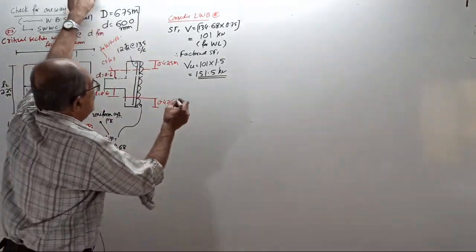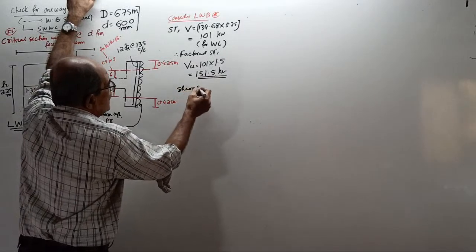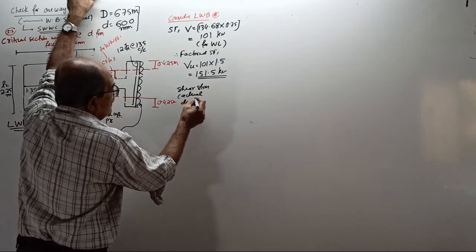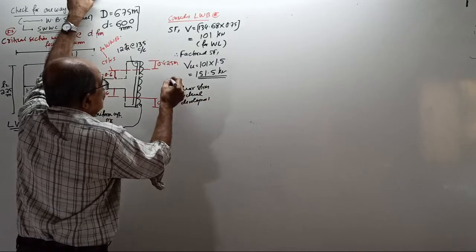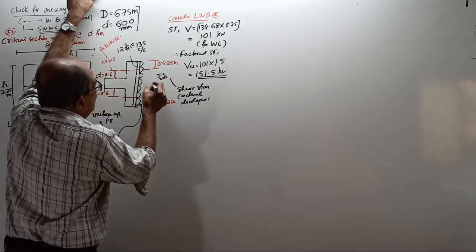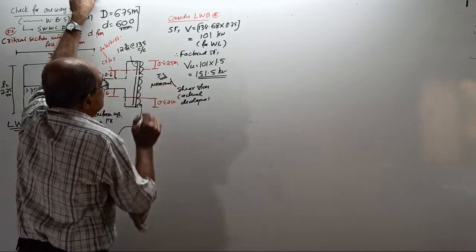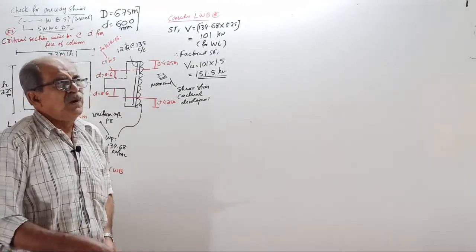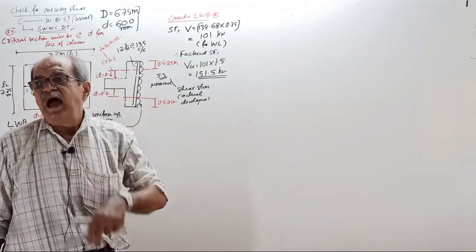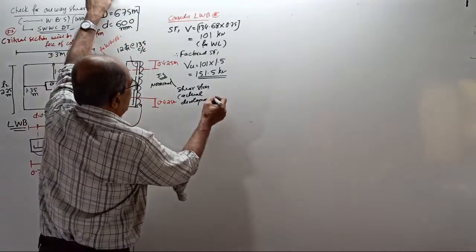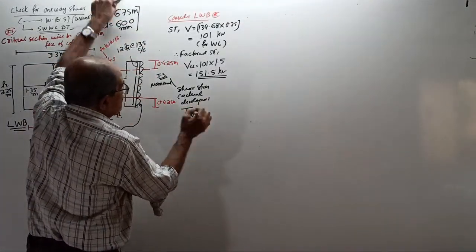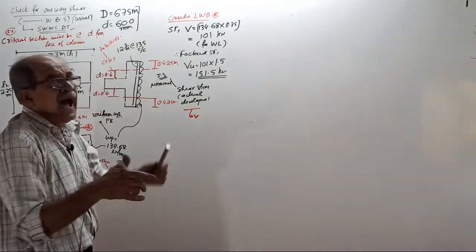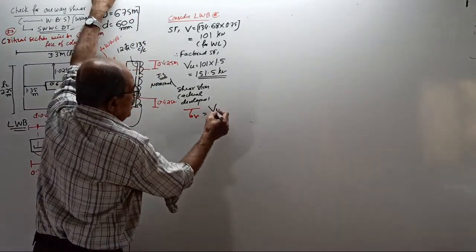Now, calculate shear stress. Shear stress means actual shear stress, the actual developed stress, which the IS code foolishly called nominal. I will use the same word. I will tell them the word nominal. Learn English and print IS code. Okay. That is tau V. This is the real stress. Remember, tau V is the danger. Why? More stress is bad.